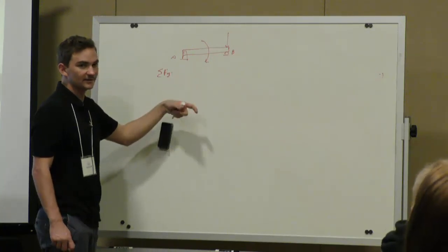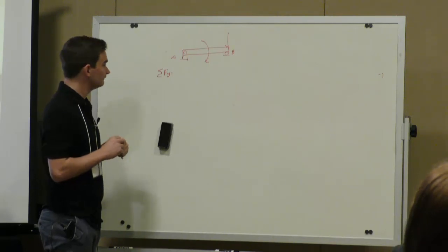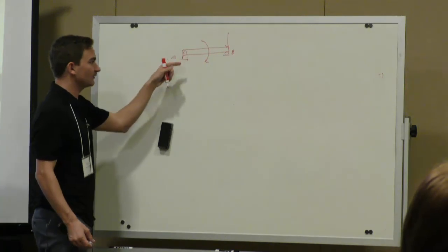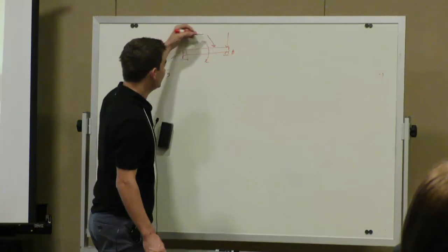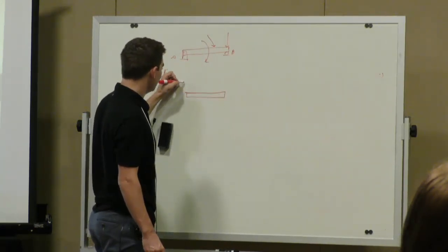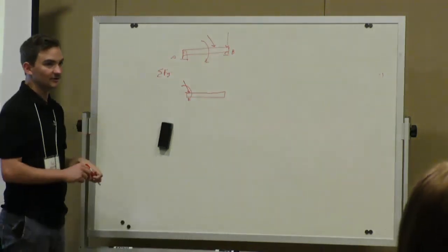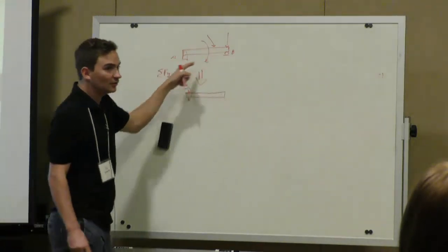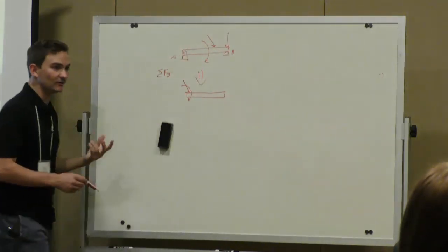However, for equivalent systems, you just solve for the magnitude, or the total, the summation of it all. Does that kind of make sense? You're not solving for the reaction force, you're solving for an equivalent system. So if you had a bunch of forces, you want to make it into, say, one force and one moment, acting at one location. That's the purpose of equivalent systems: you're trying to convert numerous forces into one force, and we only have one moment here, but into just one equivalent moment.